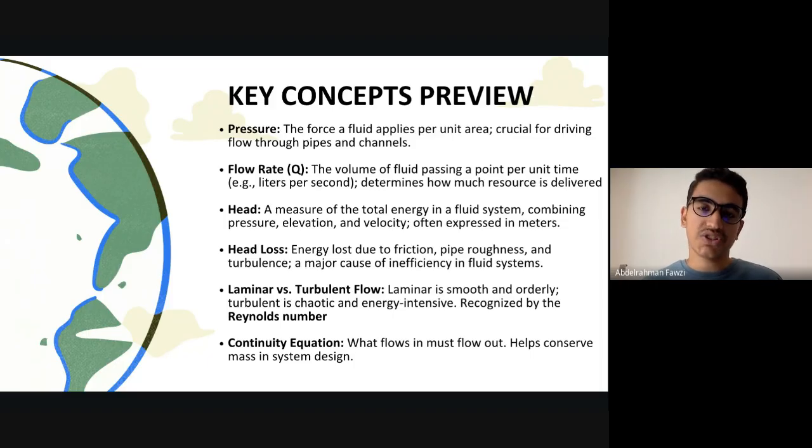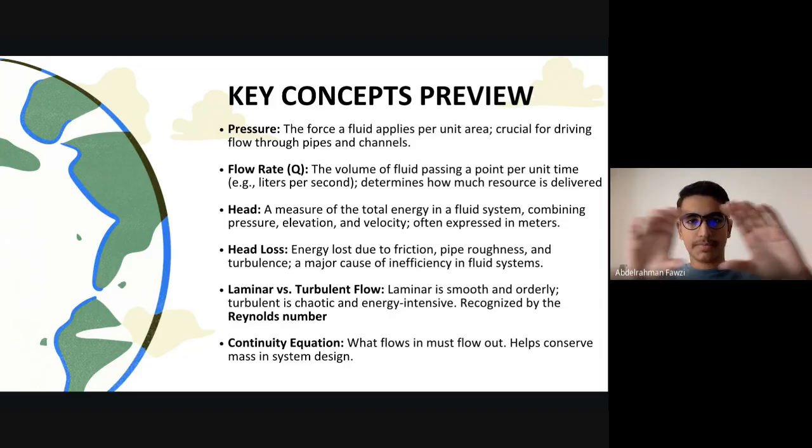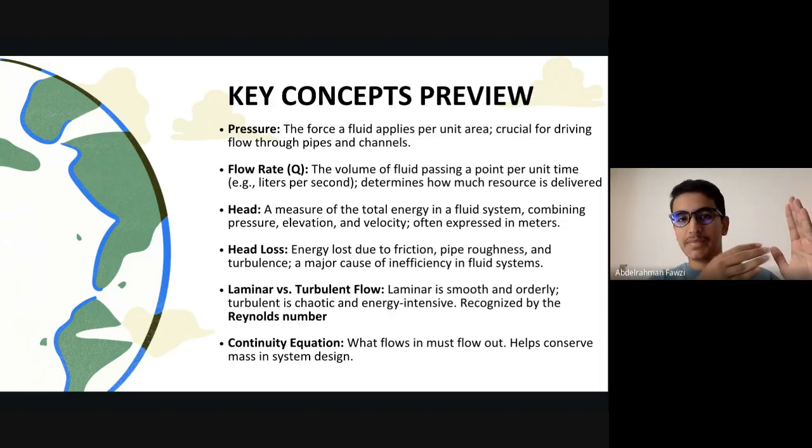And the continuity equation. The continuity equation actually makes lots of sense, but you need to consider it because, in any fluid mechanics issue that you're going to deal with, you must consider this concept because it is literally the conservation of mass law. For example, you have a pipe, you have point A and point B. If the flow at point A is 5 liters per second, then the flow at point B must be 5 liters per second as well.